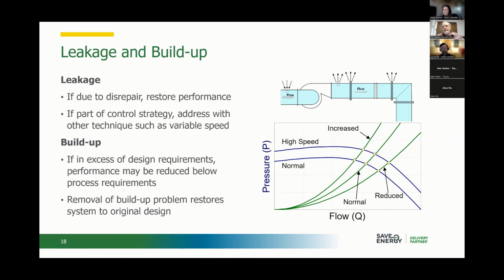And what had happened was, and if I can just show this elbow again, you can see this turning vane in here. This little dust collector had small little pieces of yarn that he was trying to exhaust. And these yarn pieces had kept looping over the vanes in the turning vane on the elbow until there was simply no gap left in the elbow. And we came to the first elbow with a pressure meter, something like this, and it was like 20 inches water gauge around the elbow. And I said, you know what? I think we found your problem here. Take that elbow down, clean the elbow up, and we're good to go.